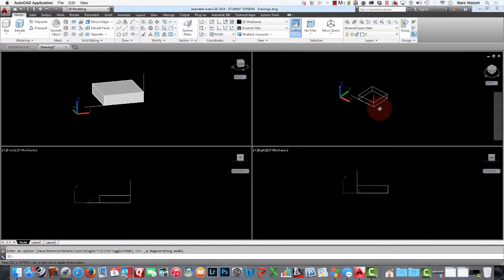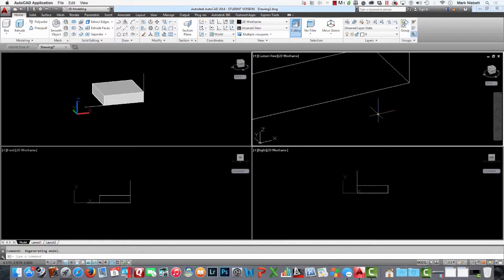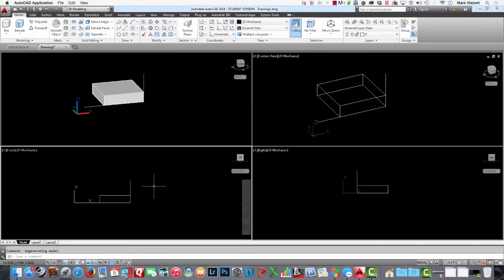Up here we can see here's our isometric here that we were looking at before. So over here we're going to use the offset command 0.3, and we'll pick the side to offset like that, so you can see that happening up here. We can see that the slot is using the center, and it's 1.2 at the bottom and 1.8 at the top of the slot. So we're going to use offset to offset this line over 2 inches, so we have the center, and then we're going to offset it to 0.6, okay, like this.